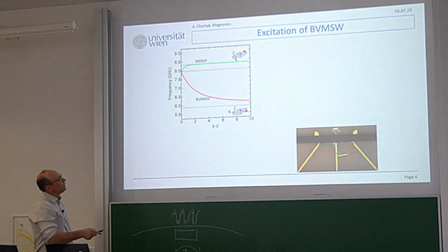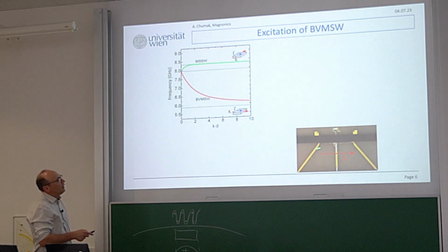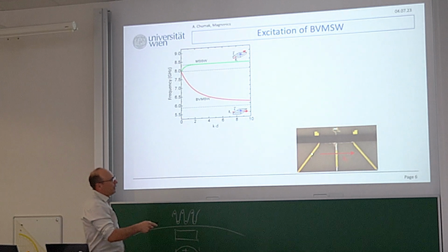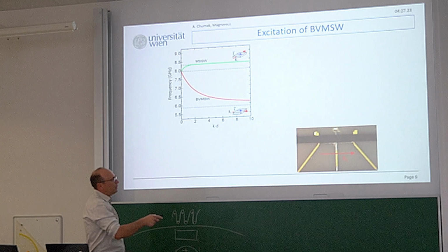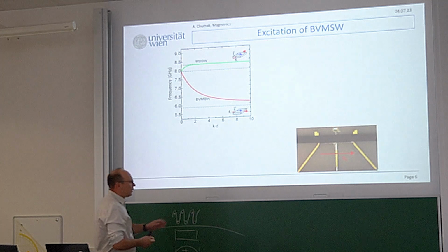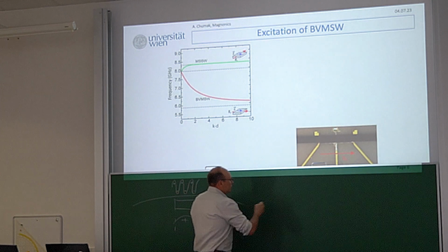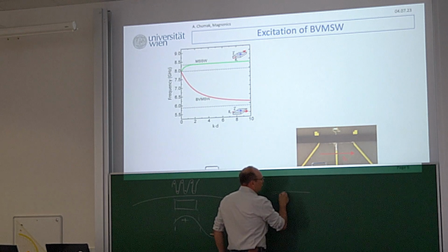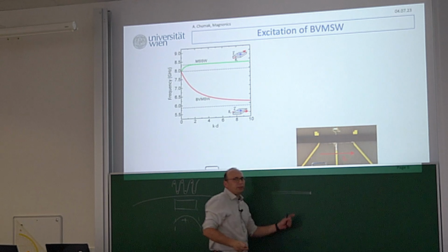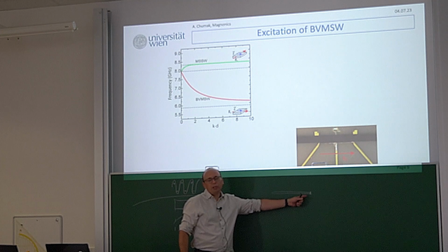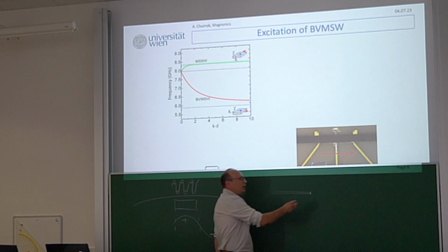Here is another antenna, also a microstrip antenna. Here you see a little adapter, and here is again a capacitor to shortcut it. Why do we need the shortcut? Because if you have an antenna, a microstrip antenna, you will anyway have some reflection or standing wave. But if you have a shortcut here,